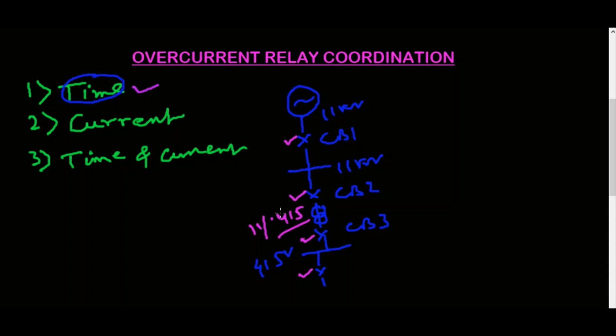So whenever we are talking about the overcurrent relay coordination with these protective devices like CB1, CB2, CB3, and this outgoing breaker, suppose CB4, that means we are going to coordinate from the downstream towards upstream. This is the basic principle of protection coordination in a power system network. You need to set the relays or the circuit breaker. If the circuit breaker has the inbuilt release feature, I have already made another video for this LV circuit breaker release feature. That means the ETU, or electronic trip unit, will be the built-in feature of this low voltage circuit breaker.